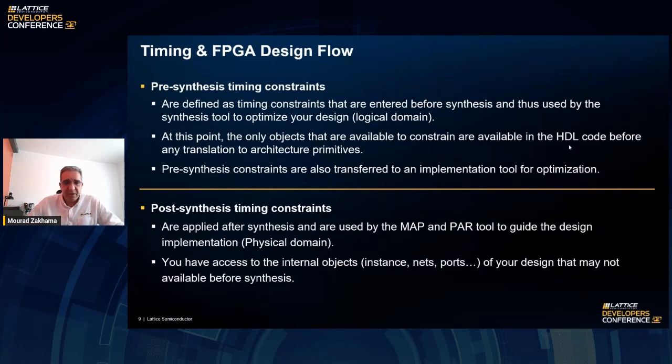different device families. On the other hand, the post-synthesis timing constraints are applied after synthesis and are used by the map and the place and route. We're going to see a diagram in a later slide showing where they are input in each stage of the implementation. They apply to the physical domain.